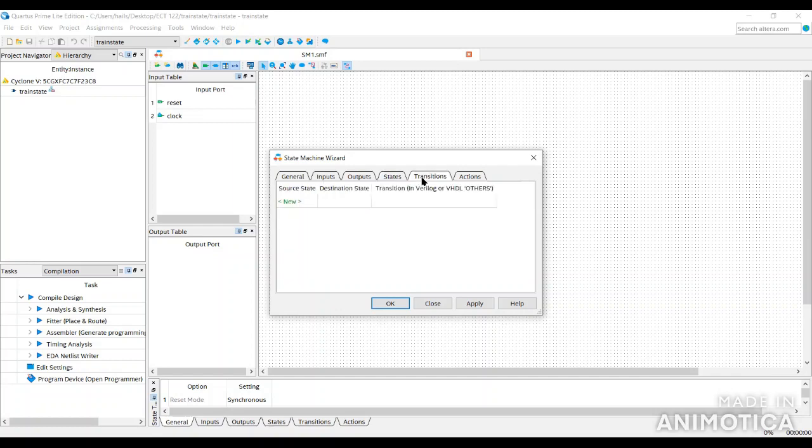The transitions are what's most important. Whenever an input is activated, it must be typed as that sensor. For example, when going from A out to A out, S1 and S2 are 0, which is signified by a tilde. Also, when there are two inputs being shown, you must use the ampersand symbol, which is used to represent that both inputs are being used to get from state to state. You replicate what was seen earlier on the table on the state machine wizard.